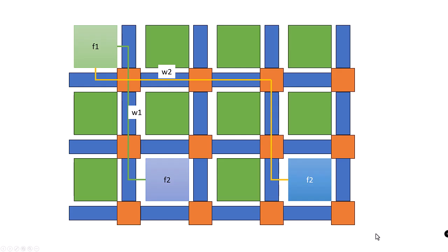Physical design includes placement of the logic into logic blocks in the FPGA and routing of the signals that connect the logic. Here, F1 is connected to F2. The two different placements of F2 relative to F1 give different routes for the wire that connects them.